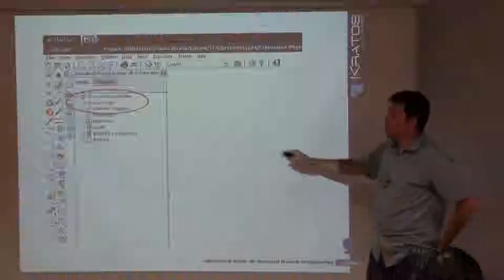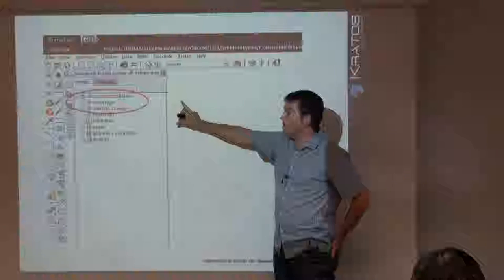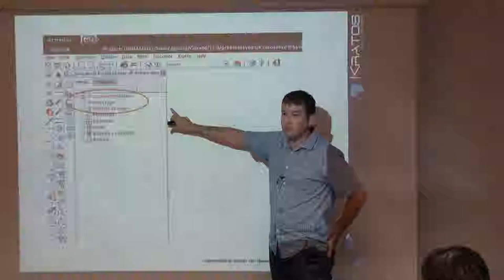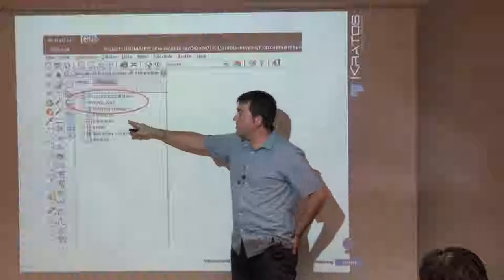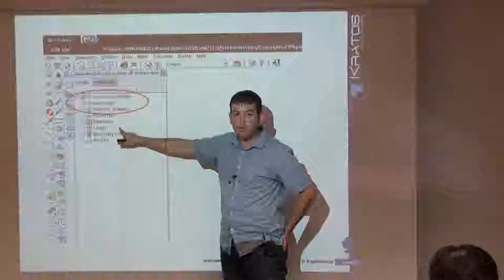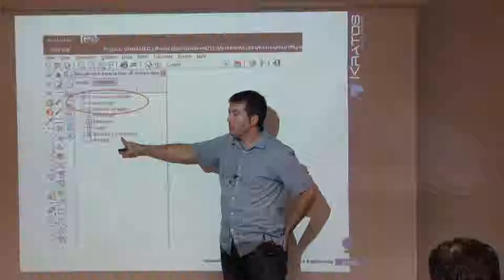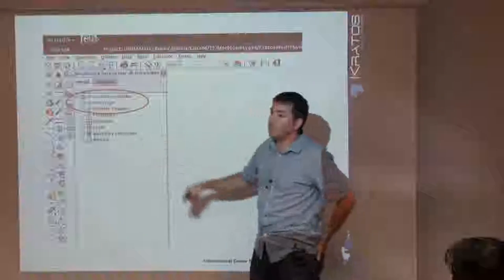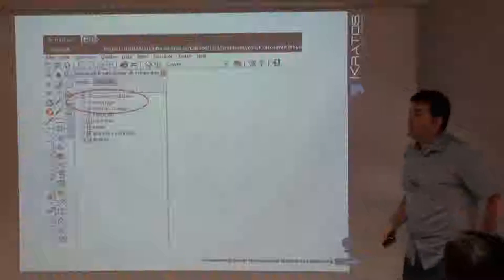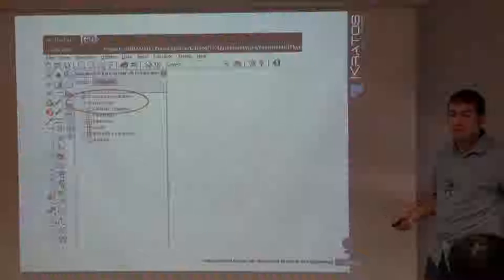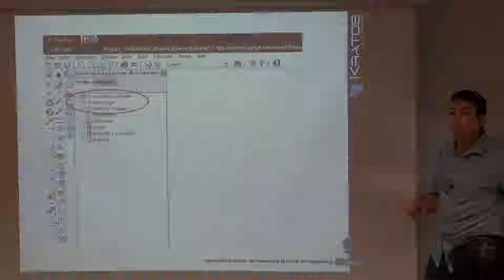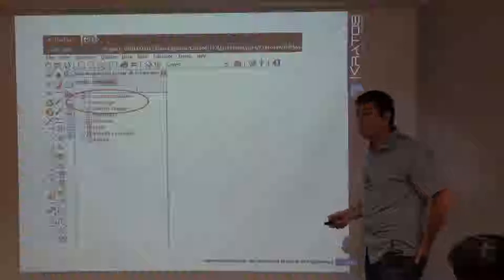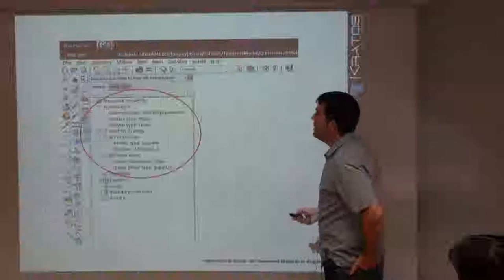The thing is that, well, this is the general structure for a finite element program, right? We have to select which elements we are going to use, which loads we are going to apply, which boundary conditions we are going to use, and here the solution strategy, well, means something about if we want to do a static analysis, dynamic analysis, and which type of algorithms we are going to use for this strategy.